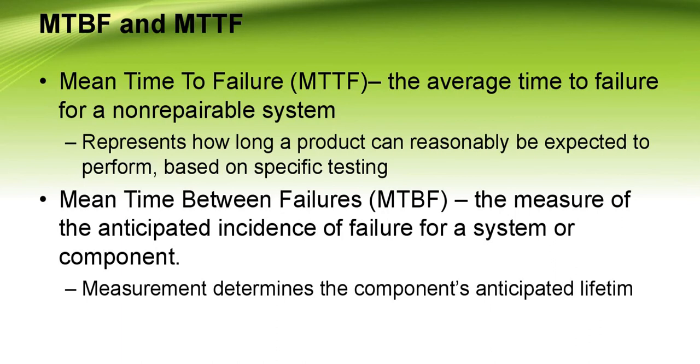MTBF is similar to MTTF. It is important to understand the difference. MTBF is used for products that can be repaired and returned to use. MTTF is used for non-repairable products. MTBF is calculated as a ratio of cumulative operating time to the number of failures for the item.